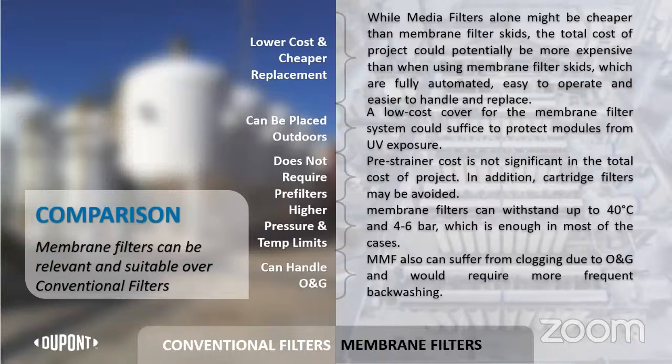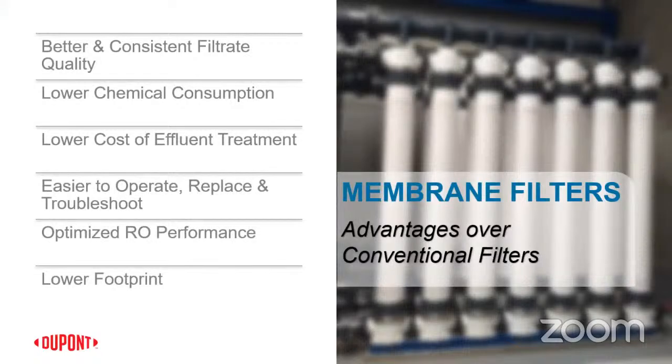And ideally, as a good engineering practice, it is wise to reduce the oil and grease levels upstream rather than letting it be managed by filtration processes. So all put together, you would definitely see that membrane filtrations have a clear advantage of being employed. So you have better and consistent filtrate quality. Lower chemical consumption can be achieved by optimal operation, because